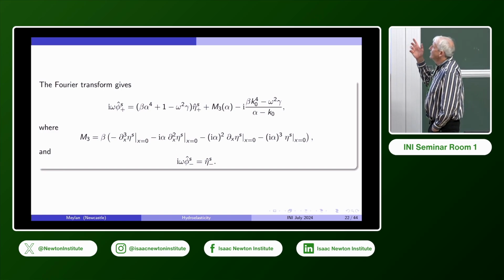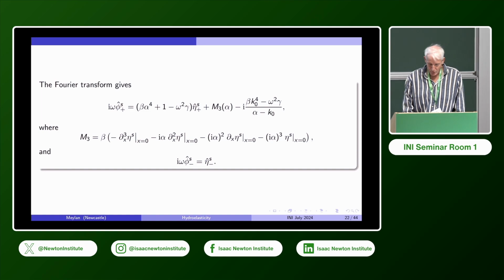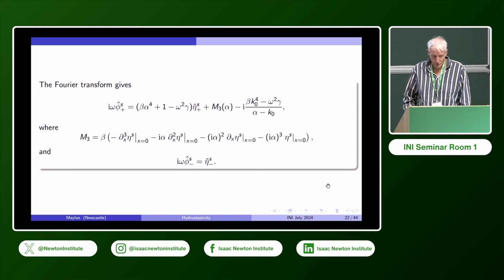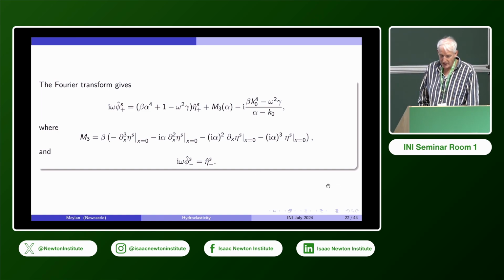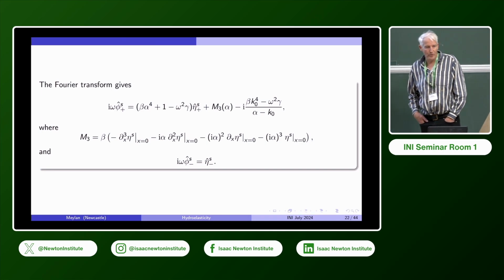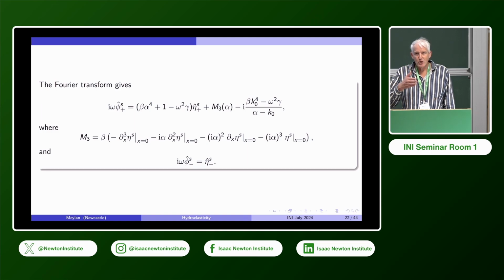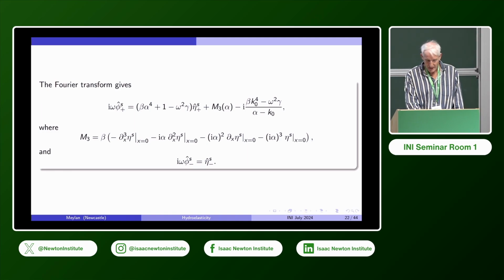Now, one solution method, which is directly taken from ideas in this Chung and Fox paper, is that they actually eliminate, and we're going to eliminate, this M3. It's quite ingenious what's done to get rid of it. I think that's because it can arise as a very annoying term in the problem that you have to then solve for as well. So you've got this unknown polynomial that appears in the equation just from doing integration by parts of that fourth derivative.